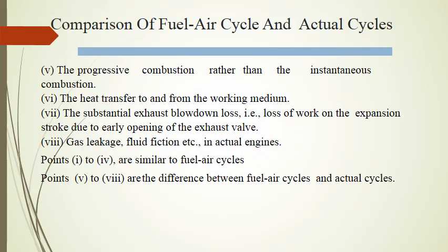The progressive combustion rather than the instantaneous combustion. The heat transfer to and from the working medium. The substantial exhaust blowdown loss, that is loss of work on the expansion stroke due to early opening of the exhaust valve. Gas leakage, fluid friction, etc. in actual engines.